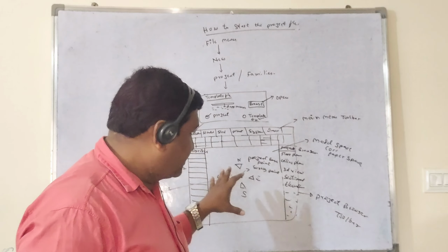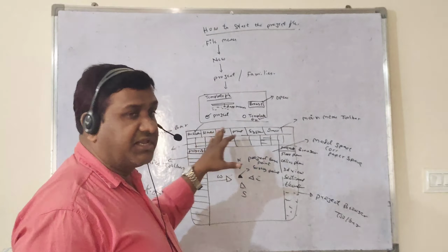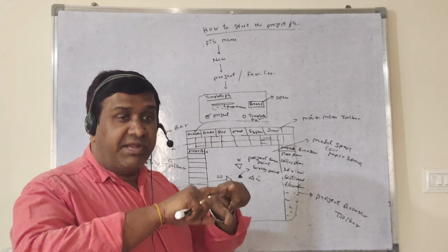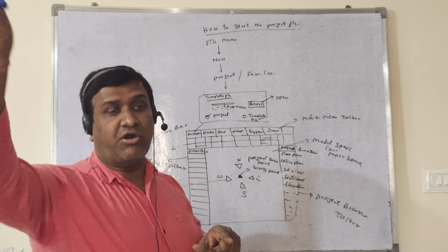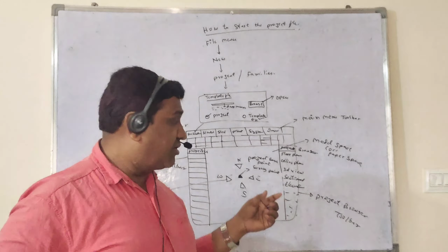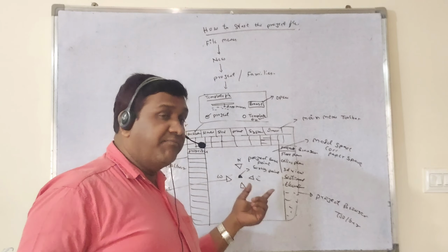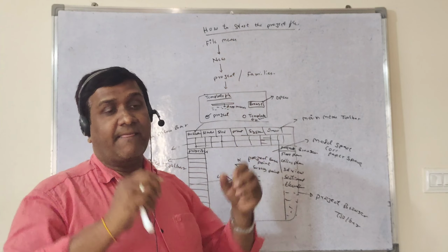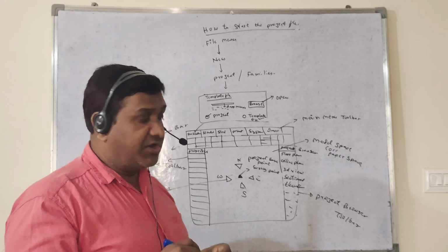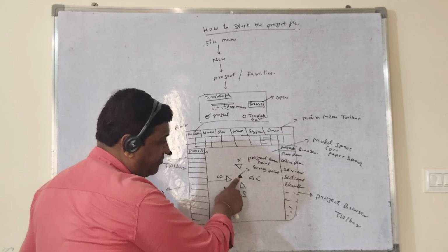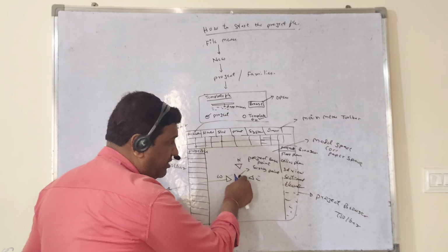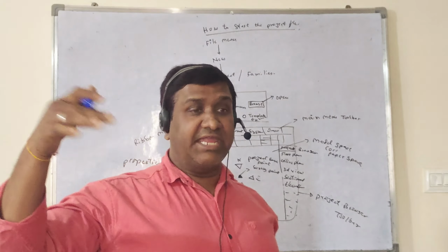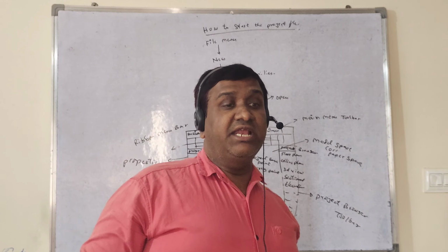Because on your screen you can see there is a lot of space. Am I right? But your project model should be developed between these elevation symbols only, not in the corner, not on that side or this side. Your project is going to be developed between these four elevation symbols. Got it? Using this project base point and survey point, you have to give the value with the help of GPS tracking location, or through the city list.